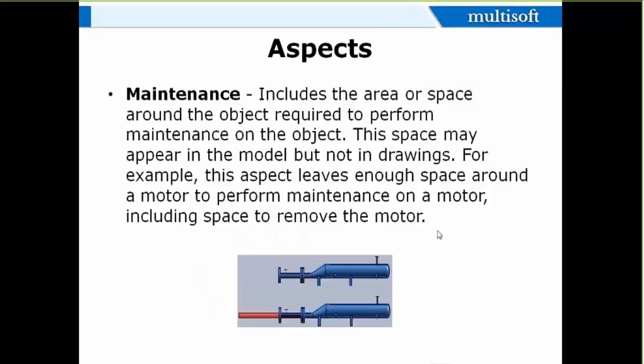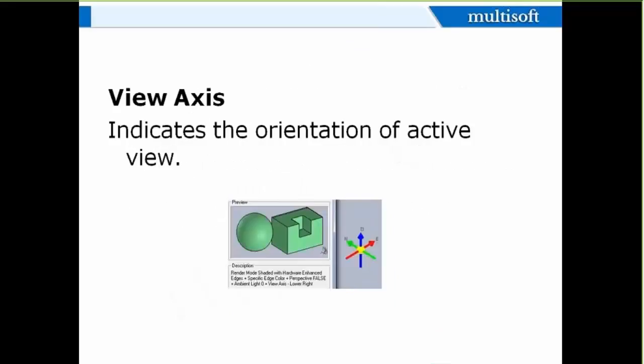And in the same way, maintenance volume, for example, see here, this is a type of aspect. Here I have modeled a small cylinder for the maintenance volume, but I switched it off. In the same way, if I want to switch it on, I can switch on the maintenance volume and it will show in this way. If any pipe is passing through this, or if I try to place any equipment here, it will throw the clash. That means it is indicating that there is an obstruction here. So please change your location. This type of smartness will help designers to make a quality model.